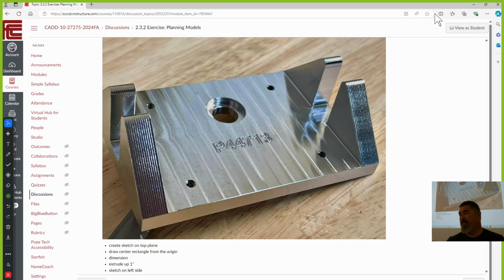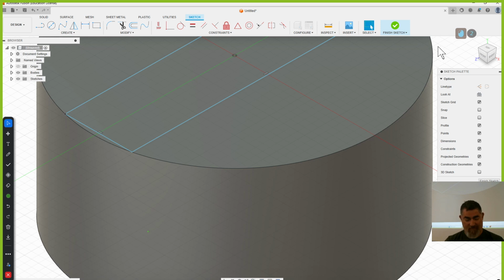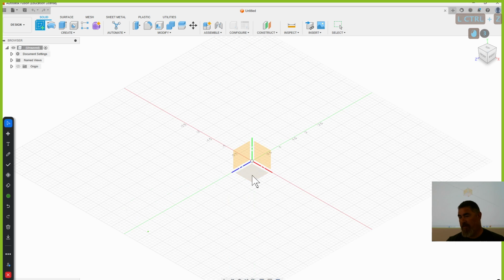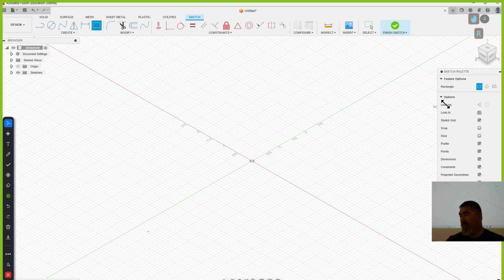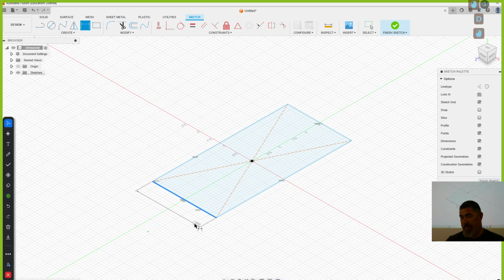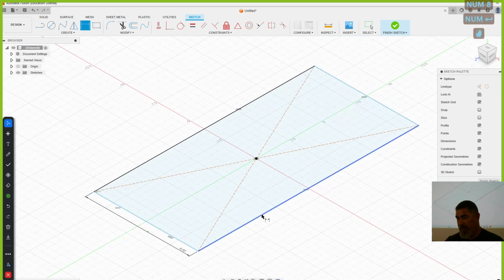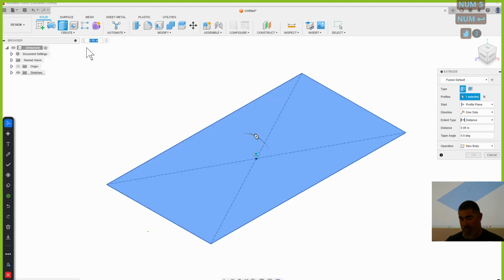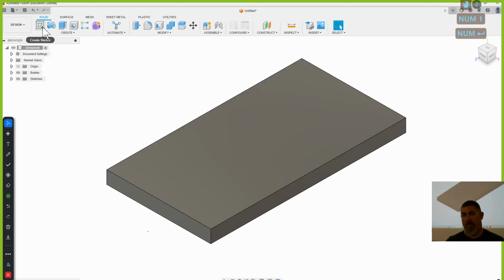Well, why not create the hole near that? What hole? The threaded holes. Because I can do those all in one sketch easy. Oh, okay. Yeah, you just point them out. So let's do that. You can just center rectangle, center rectangle. Got your 4 points. Let's say I said 8 by 15. Finish, extrude 1. Yeah, it looks okay.